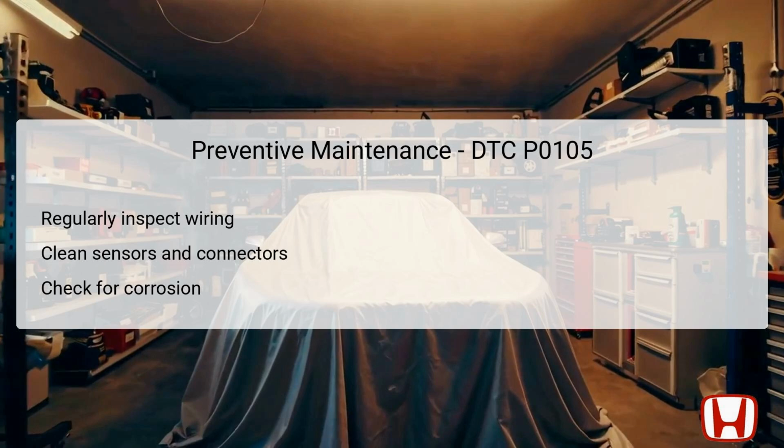Preventive maintenance is crucial in avoiding future occurrences of DTC P0105. Regular inspections of wiring and connectors associated with the map sensor can help identify wear or any developing issues before they cause significant problems.